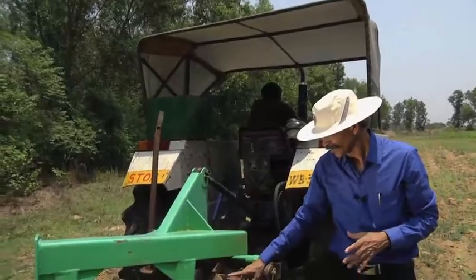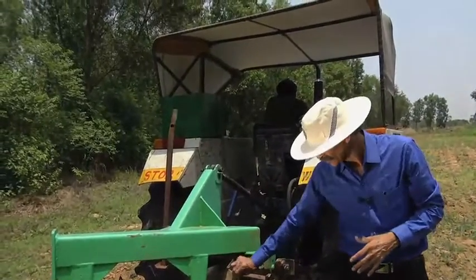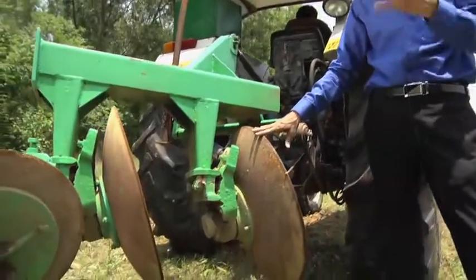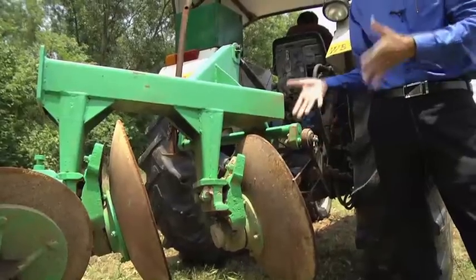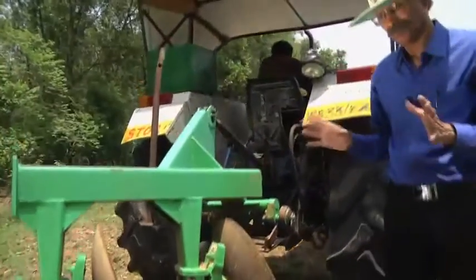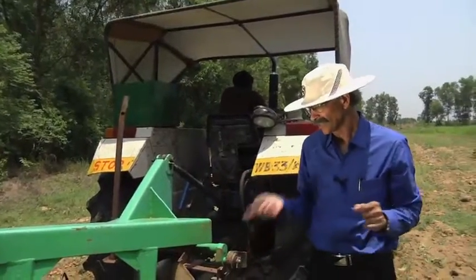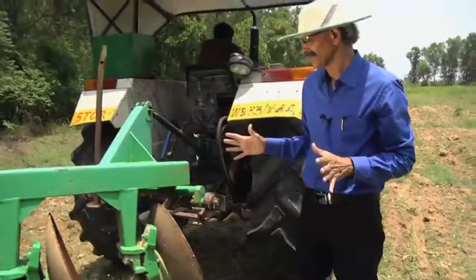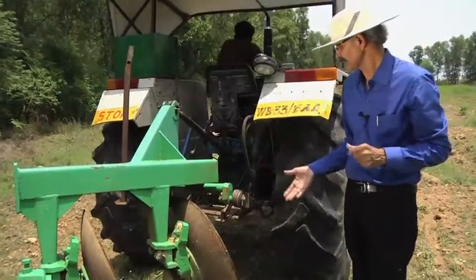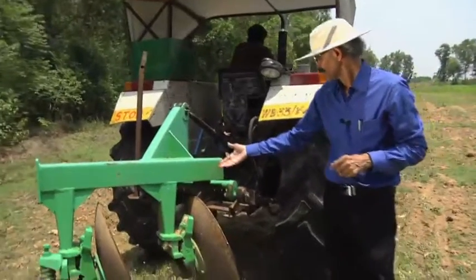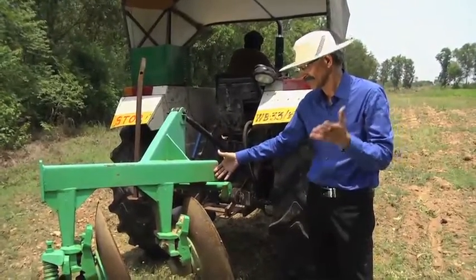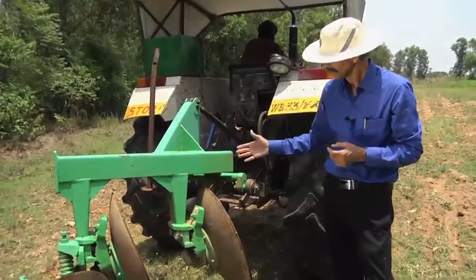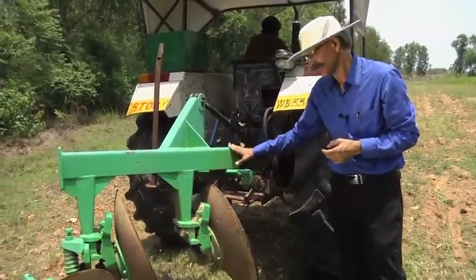Why it is important is that in case of stony ground, this disc rotates. Since it rotates, there is no problem in operation, but had it been a moldboard plough, the plough would virtually break if the ground is very stony. That is why for primary tillage, these two implements, the moldboard plough and the disc plough, are used for first ploughing of the field. Now, we will see the operation of this. It is lifted by the hydraulic system of the tractor, as I told earlier, and its position will also be maintained with respect to the tractor with the hydraulic system. So, we will see the operation of this as well.